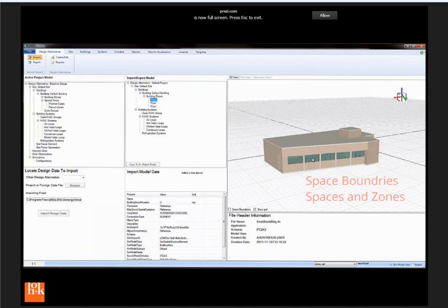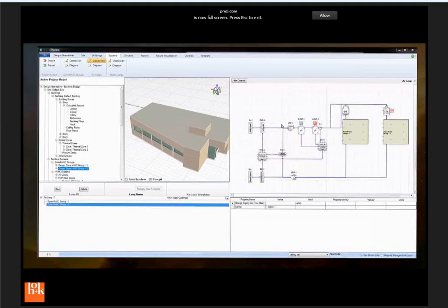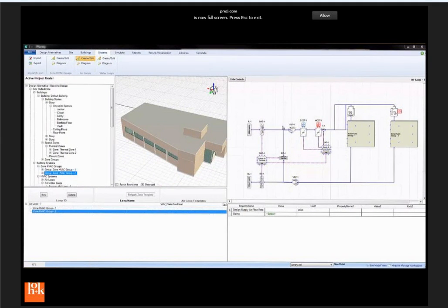So anyway, the other downside to this though is you have to manually specify zones. IFC has no concept of zones right now. So HVAC zones or exhaust zones, that's coming. I think it's part of IFC4. But currently, like I said before, there's a lot of ways to draw kind of room objects in Revit now. We have spaces. Now we link them together. We have zones, we have areas, and we have rooms. But to IFC, it's just a space. The whole thing is a space. So that's a little bit of a downfall here. And another interesting thing, I know a lot of these programs do this, but I think it's pretty cool that you can design the HVAC system graphically to put that in there.